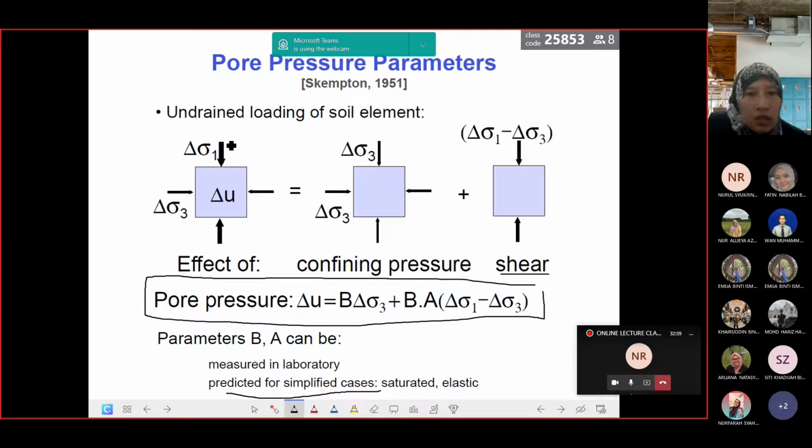Okay, these are the conditions. If you remember the chapter on consolidation, for example in CAG 461, you learned about consolidation. Consolidation is a phase where you try to make water flow out from the sample. So during that time you will have dissipation of pore water pressure. Pore water pressure will develop, you will obtain its value, and then you will see the increase of the effective vertical stress. So the best thing is that when you do consolidation, it means we have increased the bearing capacity of the soil. From fully saturated, it becomes drier, for example here.